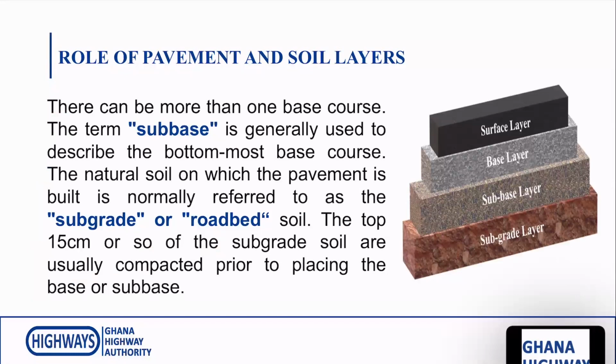The subbase is a term if you have several bases. A subbase is a term that is given to the lowest base material, which is on top of the subgrade. The subgrade is not considered structural, but the top 15 centimeters is compacted prior to replacing the base or subbase on top of it.